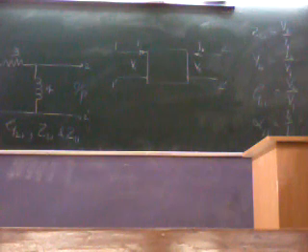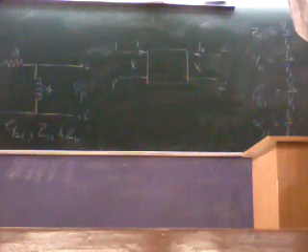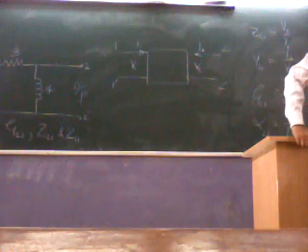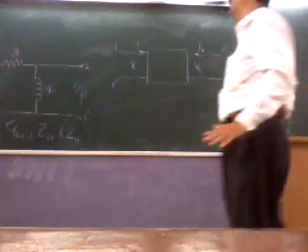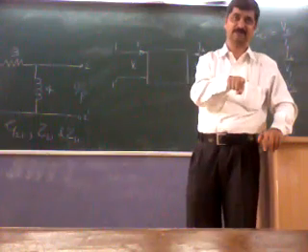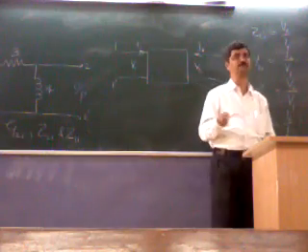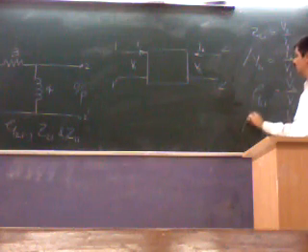So a two-port network has input and output. You may cascade it, so the input of the second is the output of the first. Effectively for a cascade network, again one is input and one is output. Ultimately you connect a source at the input and a load at the output, with multiple stages of cascading. Unless we terminate the network with some load which is not part of the network, the parameters Y21 and alpha 21 would be zero.